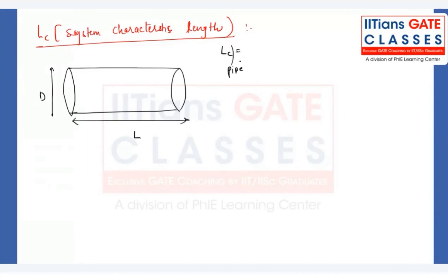If I ask you for the pipe flow problem, where the fluid is flowing in a pipe, what should be the characteristic dimension? Whether it should be the diameter or the length. That is correlated to the fluid property, or the variation of the property along which direction it is more significant. See, the length we don't consider, guys. We consider only the diameter, over which you will see the variations, right?